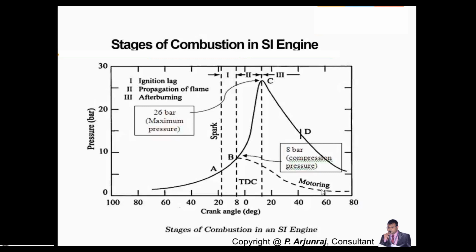Suppose you are going for motoring, where you cut the fuel, which means the pressure is going to be lesser. You should avoid the motoring, but when you're measuring the friction mean effective pressure or the friction power of the engine, mostly they do it in the motoring condition sometimes, and they also take it into consideration.